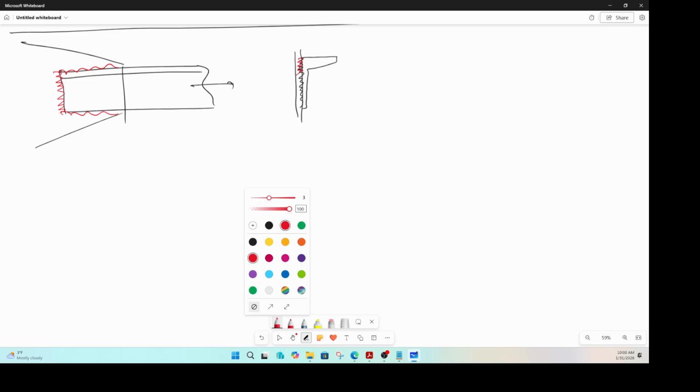Or I'll draw that in, right? So the angle is only welded here, and then force is applied. As you can see here, not both the elements of the member are connected to the gusset plate. So this load is only traveling through one element, not both elements. So the angle here is L6x6x1/2.